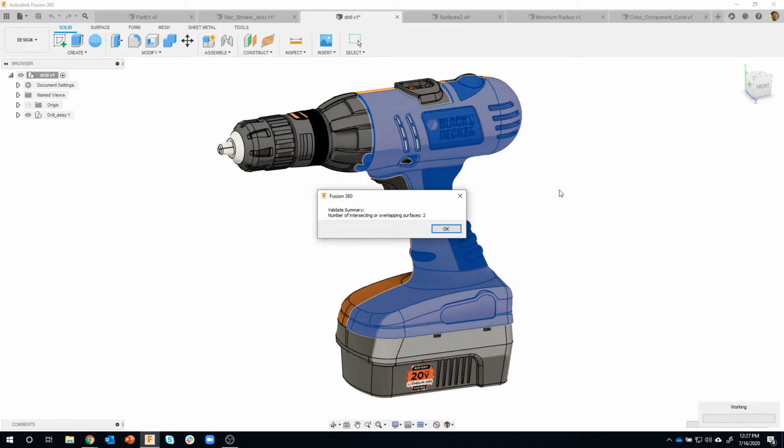So Angelo made a really cool point. He goes, I use the interference to check when I'm making soft jaws in machining. Yeah, very good point there. To see, is it clashing with the stock or with the vise or anything like that.